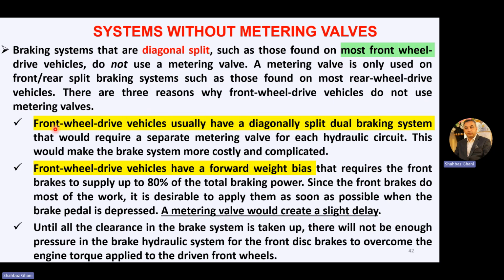Why so? Front-wheel drive vehicles usually have a diagonally split dual braking system that would require a separate metering valve for each hydraulic circuit. This would make the brake system more costly and complicated. So we do not use one in a diagonally split braking system.